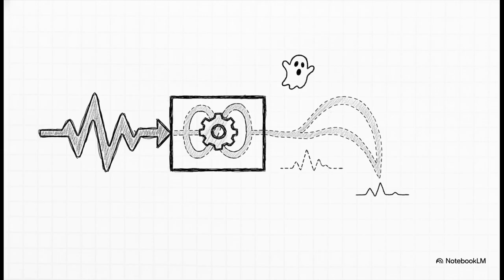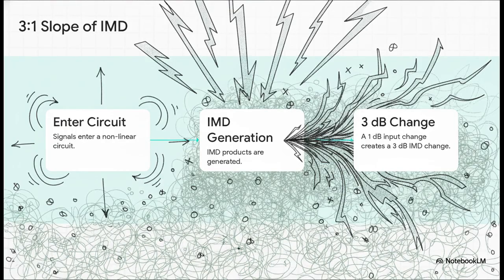These phantom signals can plop right down on top of the exact frequency where you were trying to copy a weak signal, completely masking it with a ghost broadcast that doesn't actually exist anywhere on the real band. And the terrifying math behind DR3 is based on a Taylor series mathematical model. These third-order intermodulation products don't just grow linearly alongside the interference. They actually increase up to 3 times faster than the desired signals.